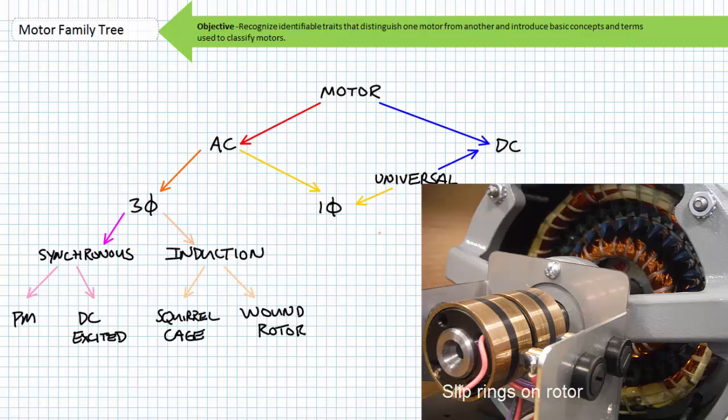Two, there exist connections to the rotor. These connections can short-circuit the rotor so it behaves exactly like a squirrel cage induction motor, or add resistance to the rotor to vary the starting characteristics and operational speed of a wound rotor motor, or, in the case of doubly fed induction generation, act as electrical inputs to the rotor as well as stator, hence the term doubly fed.